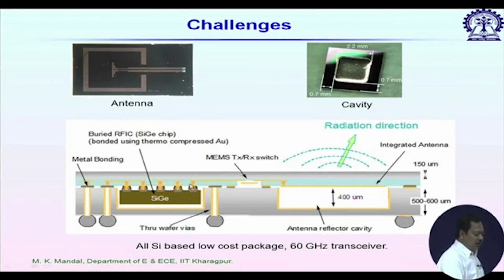Now, if I look at this chip, the passive components, typically the inductors, occupy very large area, and usually they are fabricated on the top metal layer of the chip. So, the coupling between the inductors and the antenna is expected to be maximum. That is why, to avoid that coupling, we sometimes use some sort of guard ring around the antenna structure, which will minimize the coupling between antenna and the inductors.